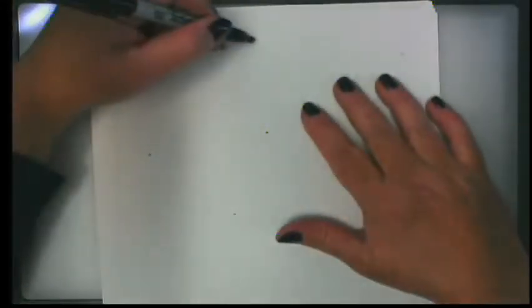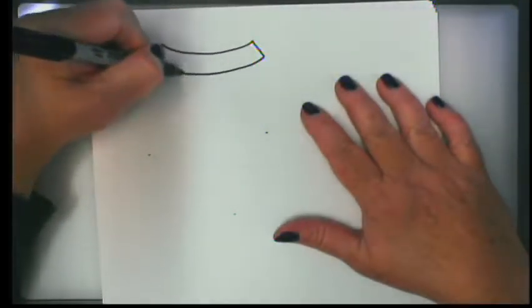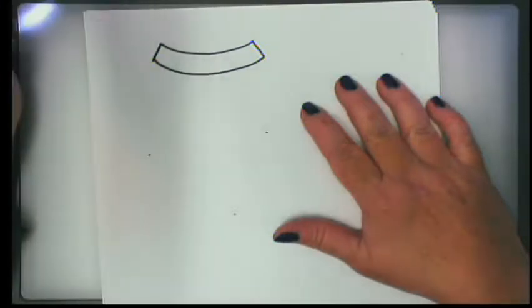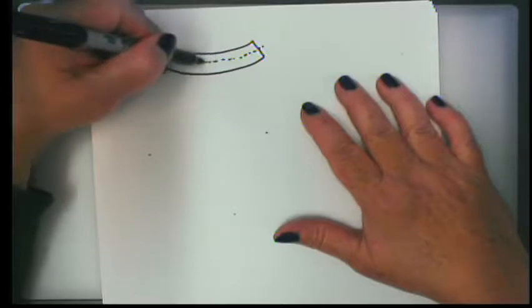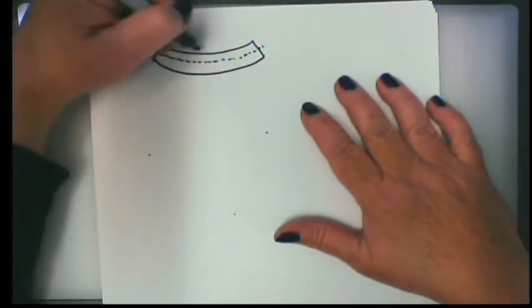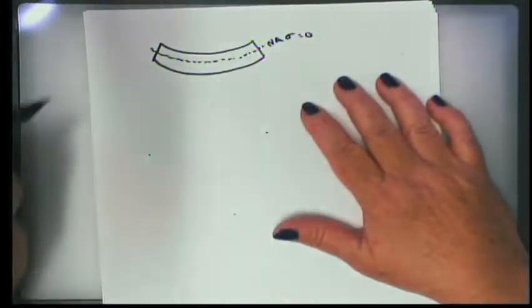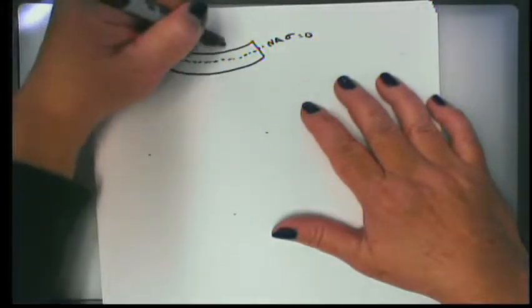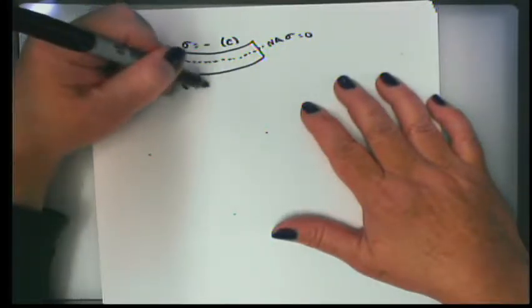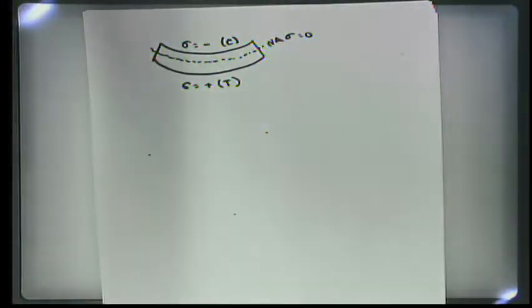All right. But we have to compensate for this problem. When we have any material, including concrete, that bends like this, what happens is, as you recall from our previous discussion, that at the neutral axis, sigma is equal to 0. Above the neutral axis, sigma is negative, signaling that we are in compression, but below the neutral axis, sigma is positive or in tension.